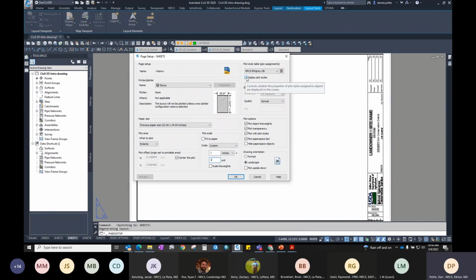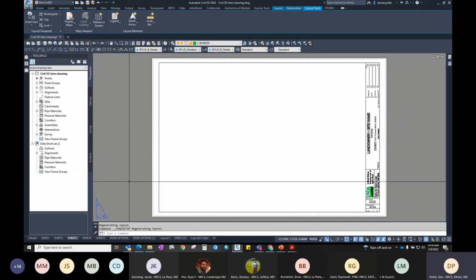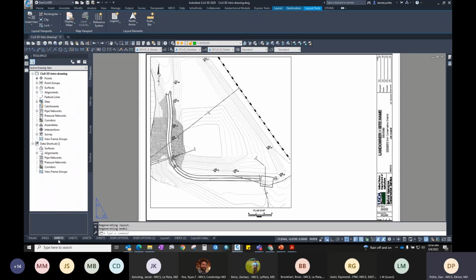And then I get some phone calls regarding, I opened up the template, or I opened up a drawing and it shows all these colors. Either you don't have the CTB set, it'll have an error on there saying that it's unavailable or something, or this is unchecked. So if I uncheck this, close this, well, it's only on that one, so we can do this one.